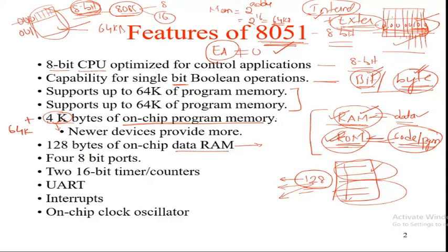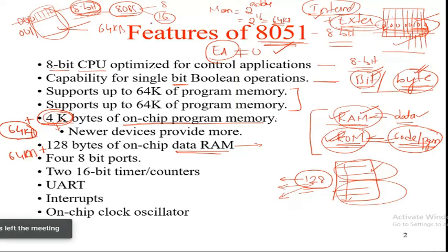Along with the internal program memory, the external program memory that can be accessed is 64 kilobytes. The data memory is also 128 bytes plus 64 kilobytes of RAM. With these 16 address lines, as the processor can access this much memory, and the 8051 microcontroller has the 8085 processor within it, externally this microcontroller can access 64 kilobytes of program memory and 64 kilobytes of data memory.